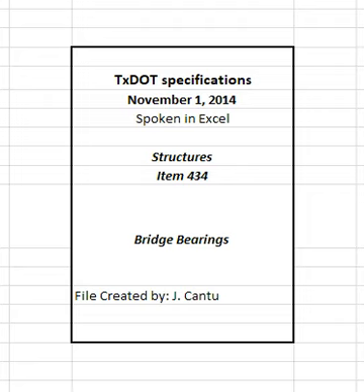This price is full compensation for the stainless steel faced top sole plate, the PTFE faced steel plate attached to the top bearing plate, the polyether urethane disc or elastomer layer, lateral guide components, shear restriction devices or outer cylinder pot bearing seals, the anchor bolts required to connect the bearing to the supporting structure, installation, and tools, equipment, labor, and incidentals.